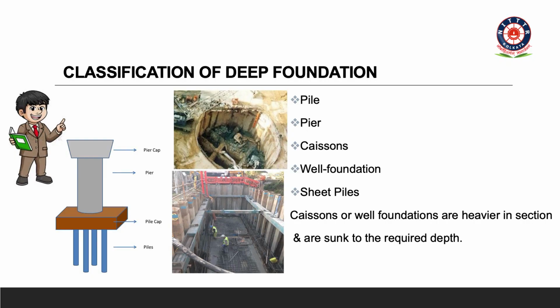See, from this you can clearly understand pile foundation acts as two components. One is a regular deep foundation concept, and it also acts like a ground improvement technique. So let me go through the subclassification of deep foundation again. One is pile, pier, caissons, well foundation and sheet pile.